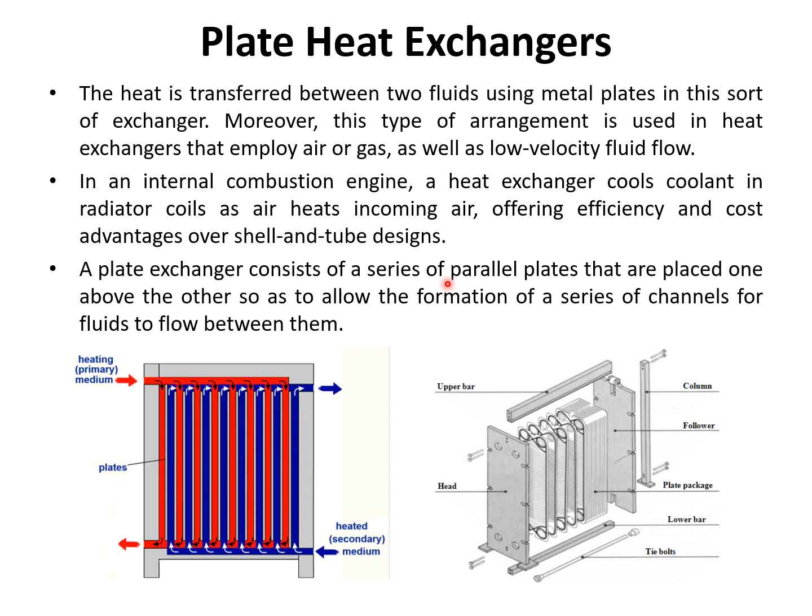Plate type heat exchanger. Plate type heat exchangers are very compact in design. Why compact? Because one plate has a good area, right? If you calculate the area of the plates, the dimensions will be a vast difference compared to a tubular exchanger. But they have some disadvantages. For example, if the medium you want to heat or cool is very viscous, you cannot use this type of exchanger. It will get choked continuously.